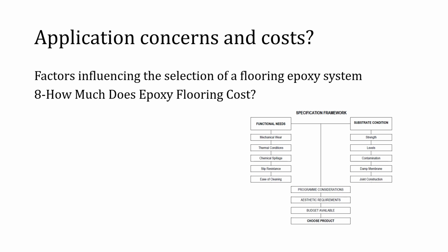Therefore, it is not possible to provide a simple guide as to where to use different flooring types, since so many parameters can affect the decision for a particular situation. However, generally types 1 to 3 are suitable only for pedestrian or commercial use or the lighter industrial situation. Where there is a regular or heavy forklift truck traffic, the thicker flooring of type 4 and above will be the most suitable. For the heaviest usage, particularly where there is a possibility of significant impact damage, then flooring of type 7 and 8 will be appropriate.